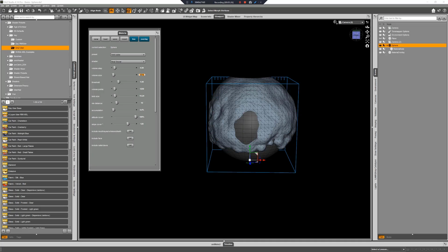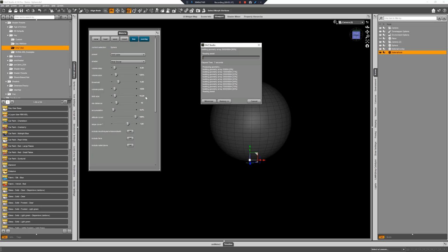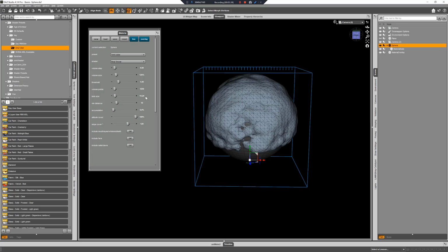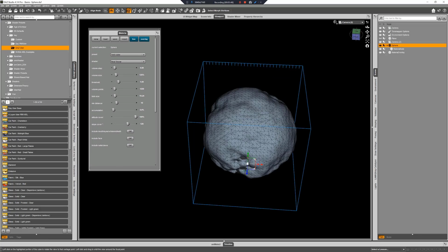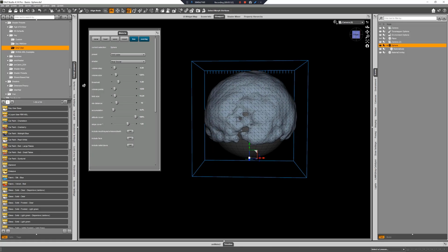So it's good advice to set it at 125 or 150. Of course, the larger the volume, the larger also the number of calculations that the software has to do. So my advice is to go at most to 150%. That should do.